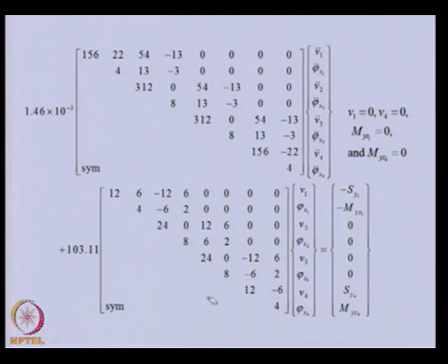Similarly, this is the assembled stiffness matrix. In the reaction force vector, the shear force and bending moment at the common nodes, 2 and 3, will cancel each other. The terms at nodes 1 and 4 will not be 0 unless specified by the boundary conditions of the problem.